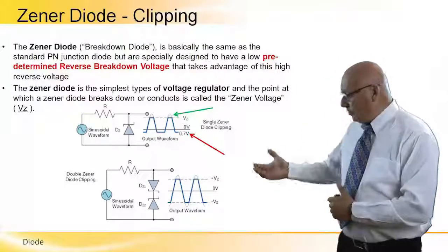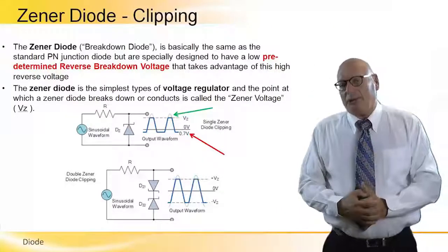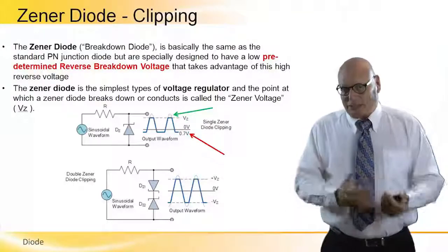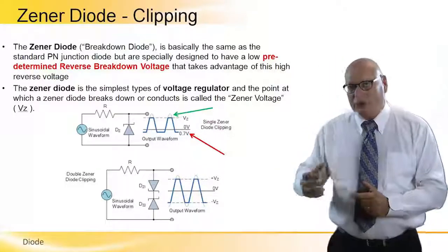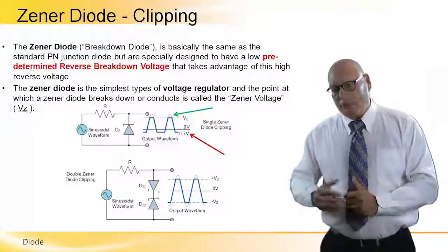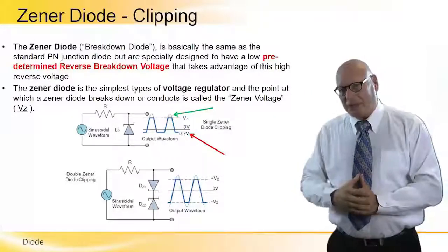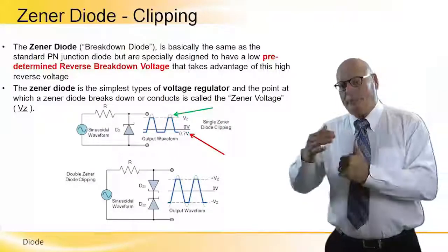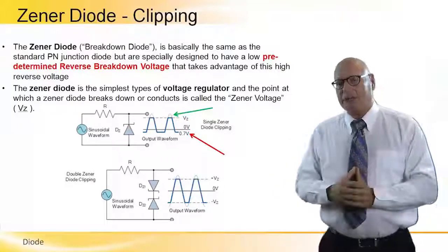However, the bottom picture shows us two back-to-back, cathode-to-cathode Zeners, which makes the operation basically symmetrical. Let's analyze that. We have a sine wave coming in. When the positive side of the sine wave goes through the resistor, the upper Zener diode will conduct, and the lower Zener diode will actually block it up to the rated voltage specified in the technical specification.